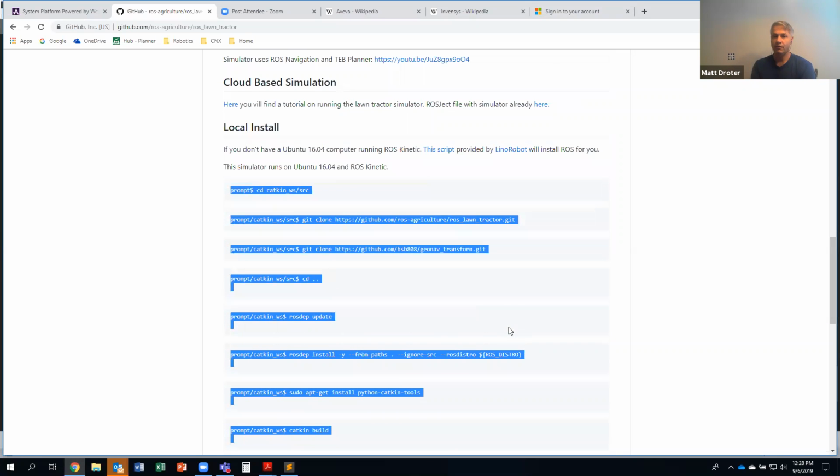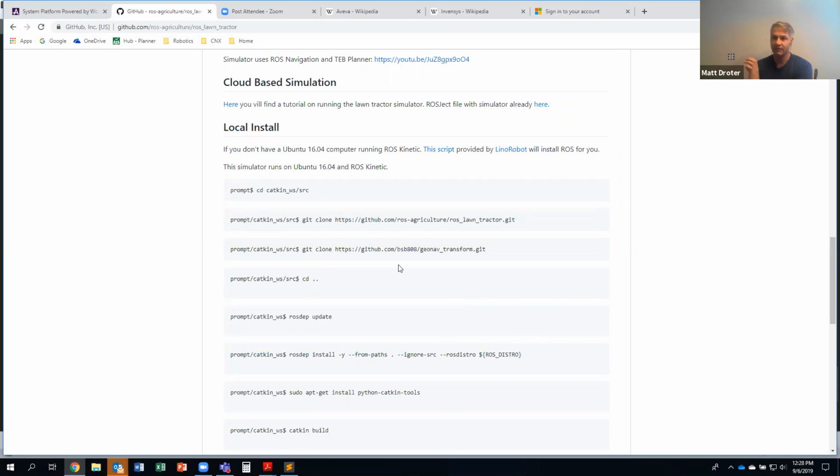If you want to. I like the simulator, and then you can play around with RQT and you can do different things running on the simulator to make sure that portion of your software is working, and then adding the hardware. So you can break up the complexity a little bit. This one doesn't have the pure pursuit one. We're still working on that branch, but this one you can still run RQT, robot steering, plot values, go through that whole process.